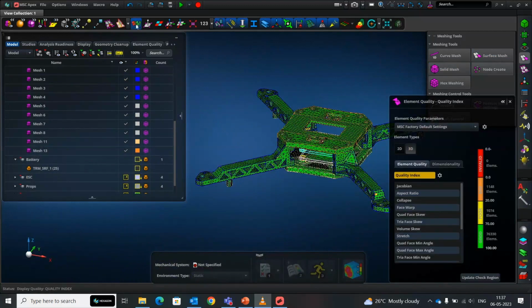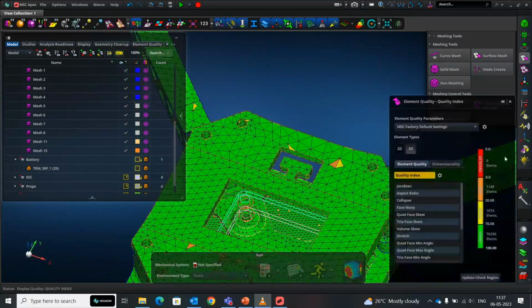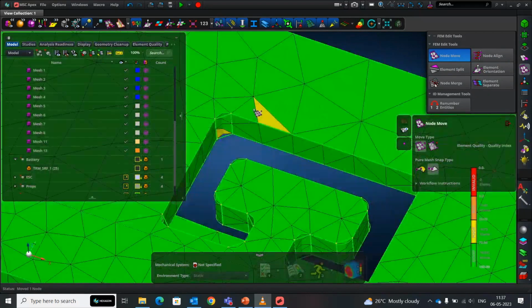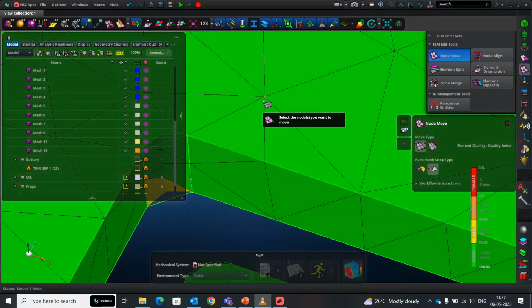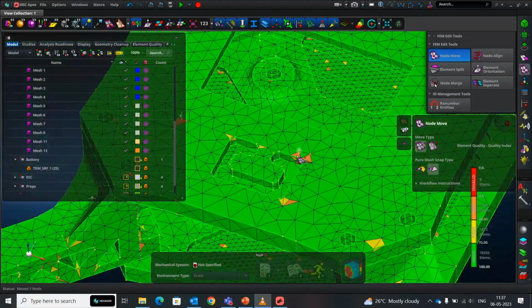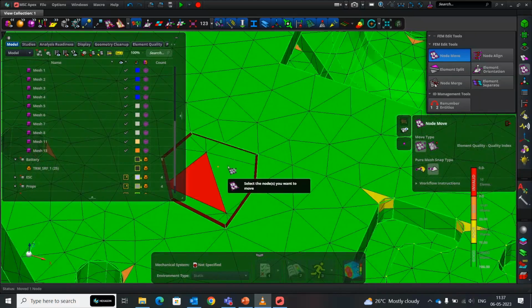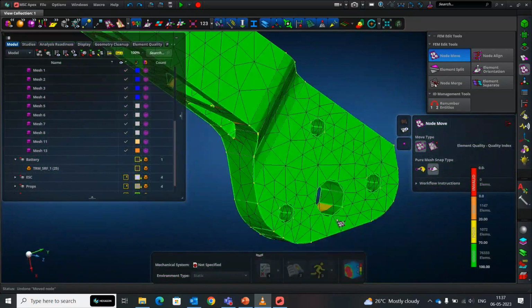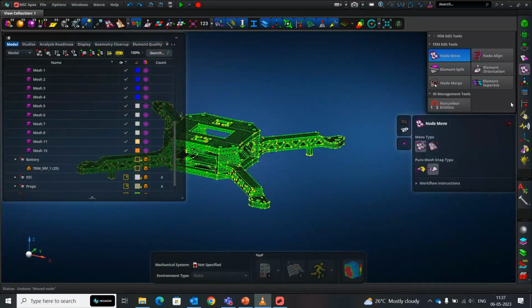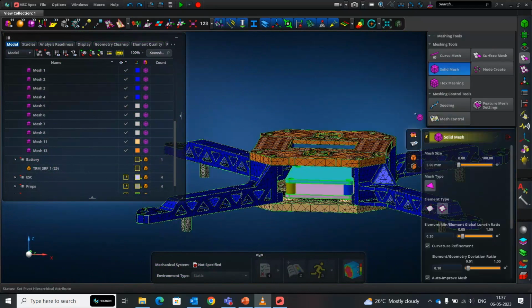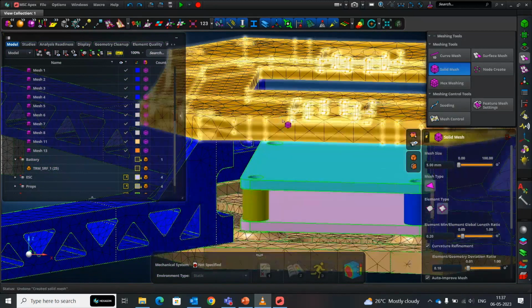So there are multiple ways of doing it. This is not the only approach. And like I mentioned, you can move nodes manually. You can see that just got cleaned up. You can move this accordingly to see what it's going to be. You have another one that's cleaned up, and then more refinement is possible. So, very few bad elements. That's an invalid element, so I undo that very quickly. As long as you don't have any invalid elements, your analysis is capable of running. It will automatically give you warnings if you do have invalid elements, and it will not allow you to perform the analysis.